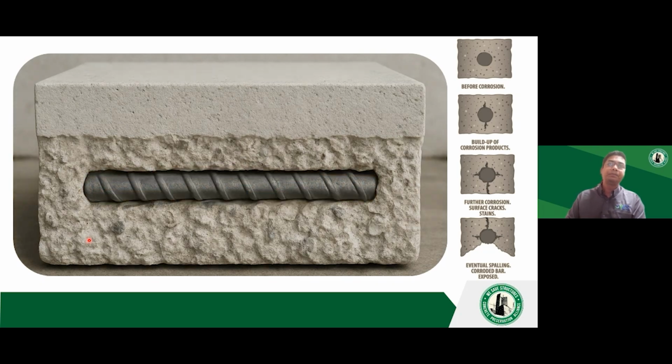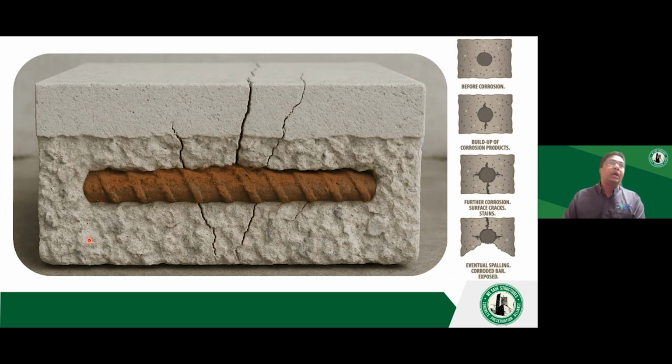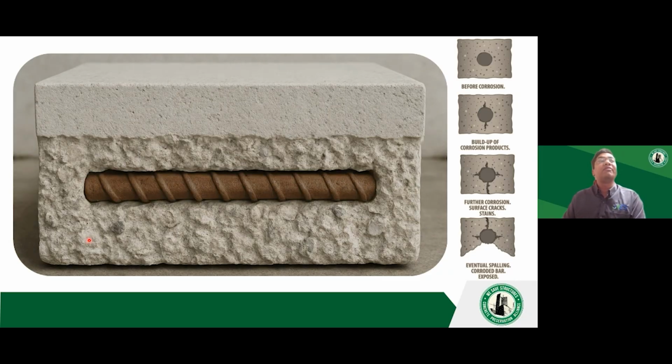That's a direct pathway. So one needs to be mindful about the cracked concrete because that's where the corrosion rates might be higher. And corrosion is such a big issue just because of the expansive nature of the corrosion products that form on the iron.